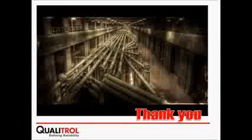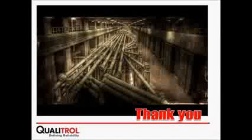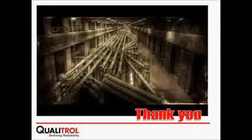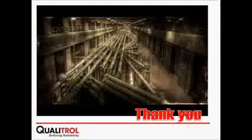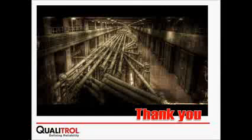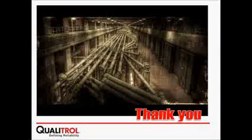And then it supports 6 UHF sensors, and I think our range is pretty wide. We cover 300 to 1500 megahertz. Many competitors cover a subset of that, so our range is very versatile. Another comment is that the best signal to noise ratio is about 1 gigahertz, or 1000 megahertz, so you need to be plus or minus 200-300 megahertz of that range. So our range is an advantage to us.